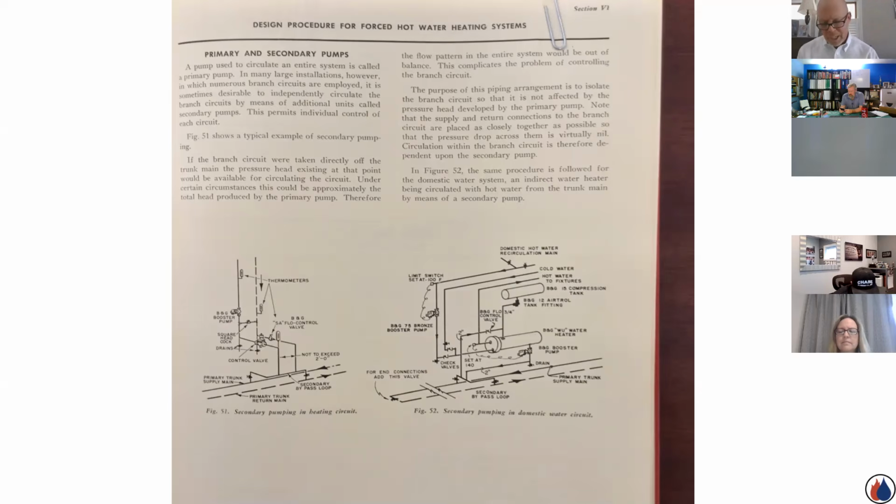So the engineers, after the phone call, called Gil into their office. I said, Gil, what'd you do? How'd you solve it? He said, I had the contractors put in smaller booster pumps that were capable of supporting the individual building loads. To which the engineers all exploded. Well, you can't do that. The larger pumps will damage the smaller pumps. And he said, well, I had them put a common pipe. I had them hydraulically isolate the loops, one from the other. And they're like, what are you talking about? So he sat down and explained it to the lead engineers at Bell and Gossett.